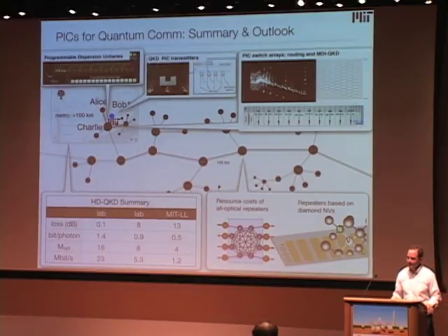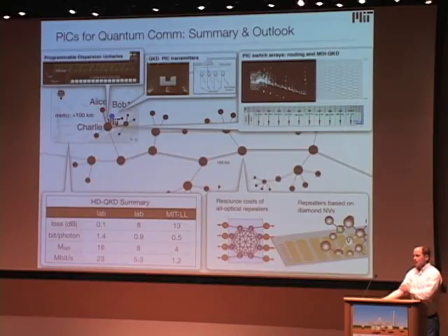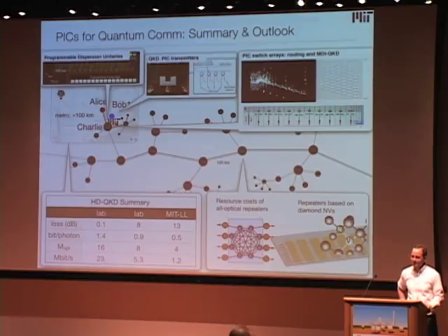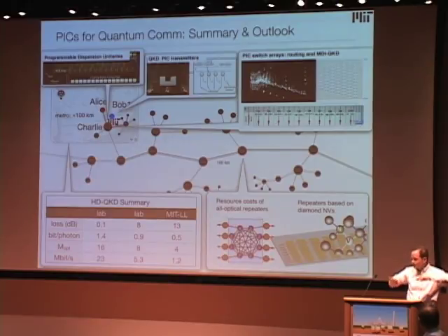One of your tables showed chip-to-fiber coupling efficiency of 0.99. How realistic is that? Yeah, so we silicon photonics people have different strategies for coupling to chips. One, in the case of an edge coupling, you basically mode match an optical fiber to the edge of a chip, and you can actually get well under 1 dB transfer efficiency. I think in the next couple of years we have some chips that should likely go like 0.1 dB or so coupling loss.